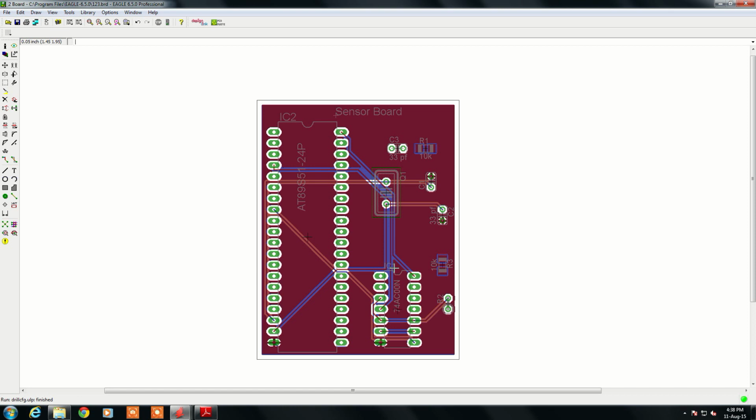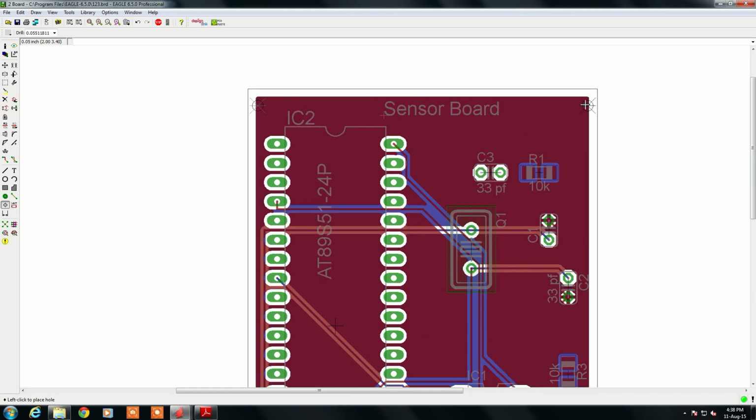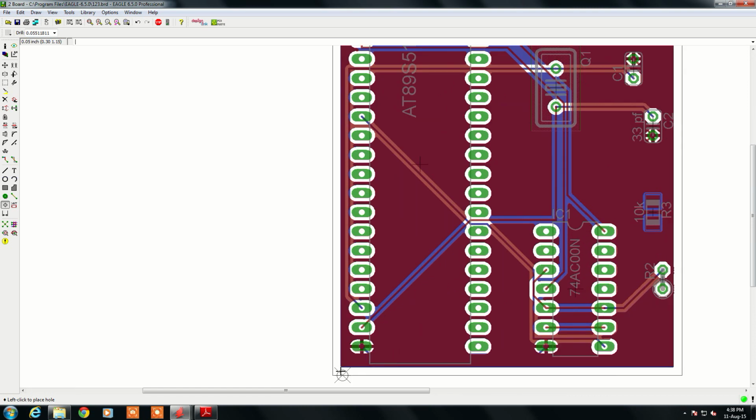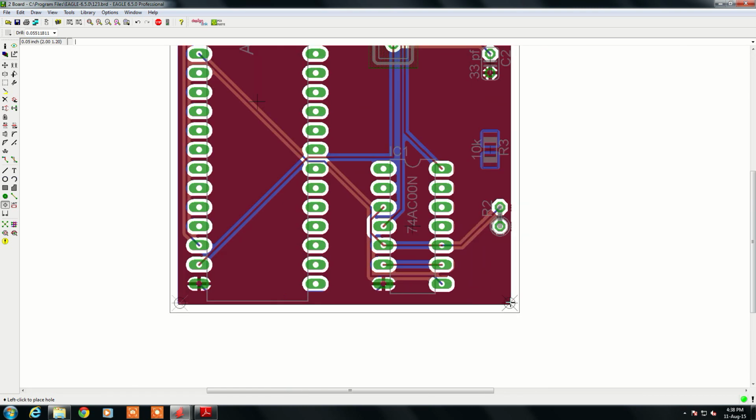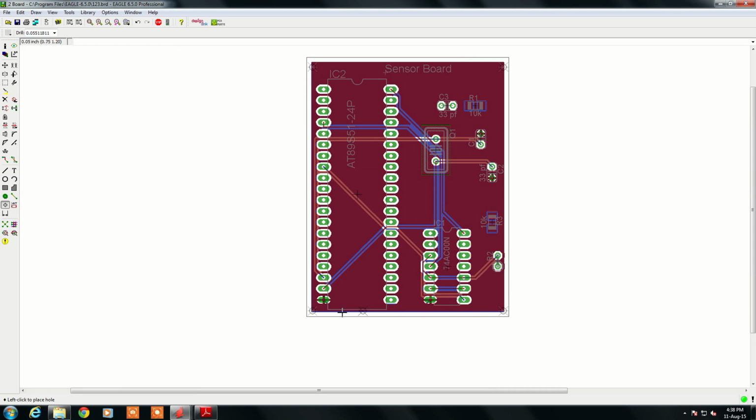While designing the PCB, you can also place some additional pads for mounting on the cabinet. Say for example, as you can see, there is a hole. So you can choose the diameter of the hole, right? And you can place them on the corners so that these are the mounting holes, so that with the help of the screws you can mount this PCB on the cabinet of your project or the product.